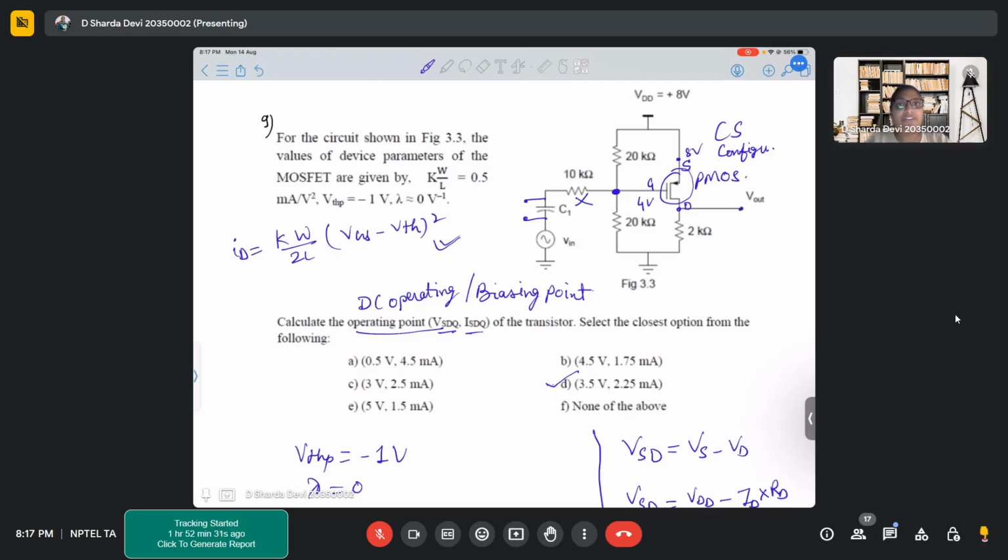And when we say that your transistor is in saturation, linear, or cutoff region, where does that come out of? It is basically from your biasing or DC operating point, like where you fix your transistor, whether you have fixed it in cutoff region, saturation region, or your linear region. Depending on that, your transistor turns on and works in that particular region.